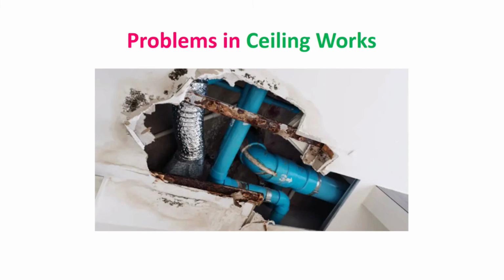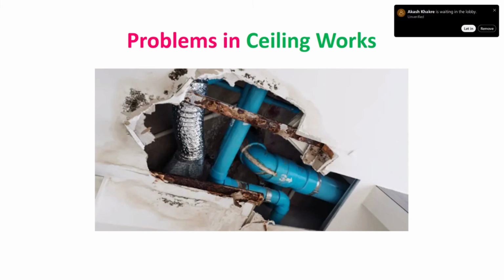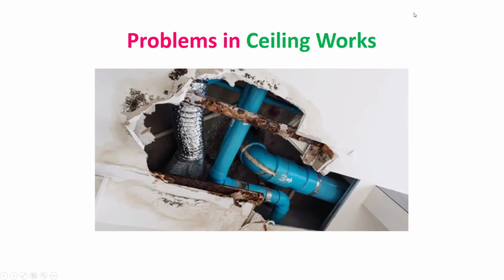Now you can see the condition of the structural members of the ceiling. That is getting corroded, and I suppose as civil engineers, although the false ceilings may be looking very good or giving good aesthetic appeal, inspection of all those hangers or whatever supporting structures of the false ceilings are there is very important, to see the structural integrity of that also. Because many times we have seen this happen, suppose they are wooden members, then due to termites it might fall down.